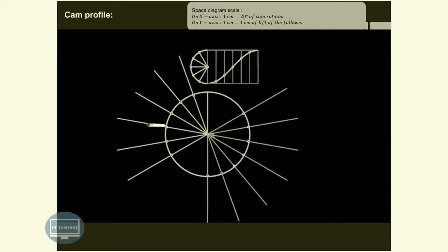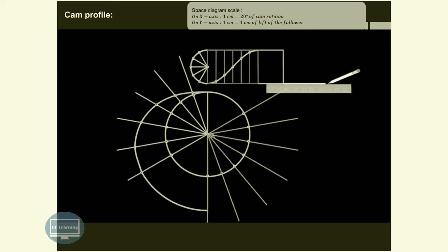Now the points which we have marked on our circle, transfer the given particular distances, as you can see over here, on those lines, and then draw a smooth curve passing through this particular point. So we are drawing these points of intersection with the line of this arc. So this is our cam profile during the outstroke. There is a dwell for the remaining degrees, so we have just drawn a curve over here.